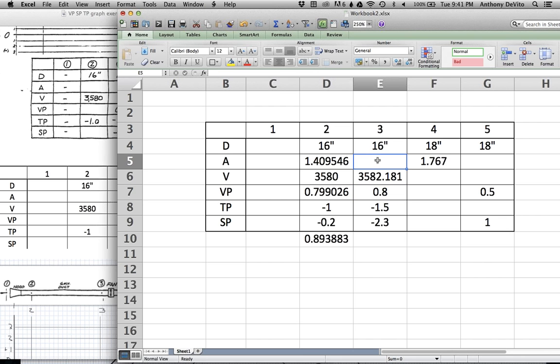Okay, so what's the cross-sectional area here? It's also going to be 1.4. Now the ductwork is going to change size. The cross-sectional area now is going to be 1.67. So what is the velocity going to be instead? Well, Q has got to be the same as it was before. So what was Q before? Let's say Q is equal to the velocity times the cross-sectional area.